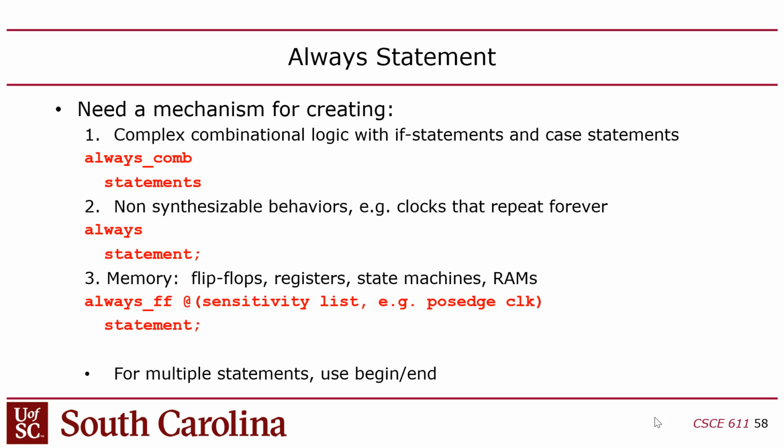Did you guys talk about sequential logic in 2.11? Okay, good. Sequential logic is when you have memory involved. That could be flip-flops or latches or RAM. Combinational logic doesn't have any kind of memory. Now, is this design combinational or sequential? This is sequential logic because when it moves the position of that LED, it's moving it as a function of what it was in the previous state. So it has to maintain memory to keep track of where the LED is.